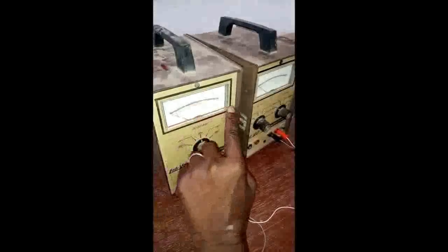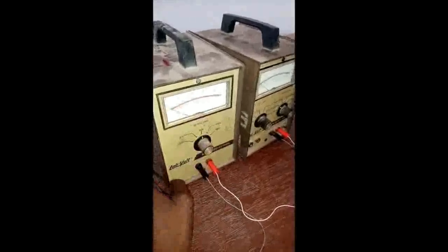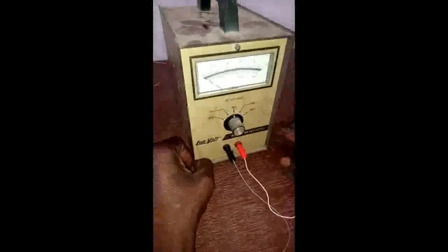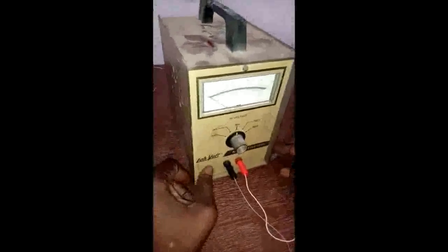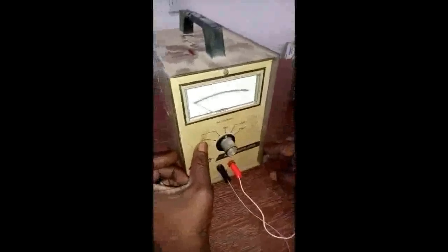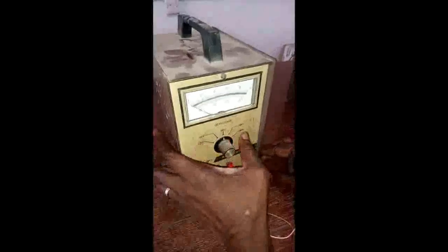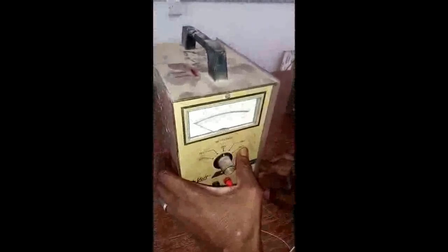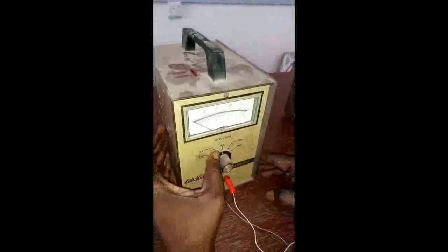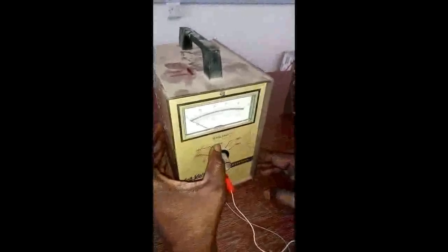This is what we refer to as panel meter, and it is analog in nature. It's a DC voltage meter. If you look at the ranges here, it started from 3 volts up to 300 volts range. Even though we rarely use the 300 volt aspect, what we normally use is that of 3 volt, 10 volt, and 30 volt, as the case may be.